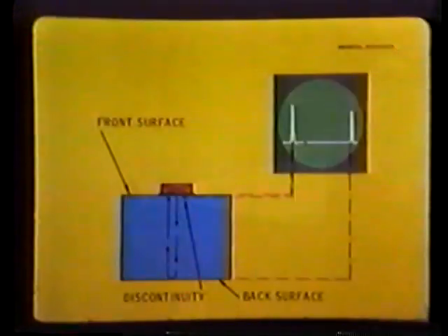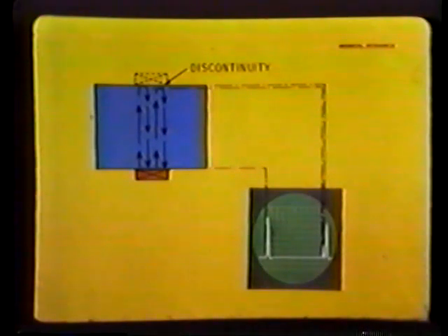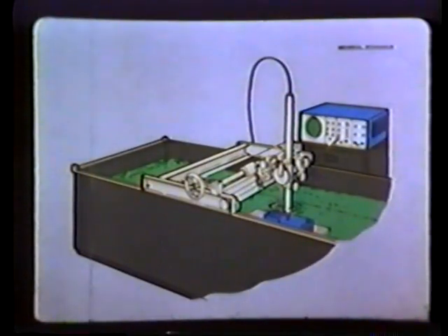The dead zone can be minimized by using a shorter or lower magnitude excitation pulse, using separate transducers to transmit and receive the vibrations, or sometimes the transducer can be moved to the opposite surface of the test specimen. Another way to minimize the dead zone, improve near-surface resolution, is to use the immersion method.